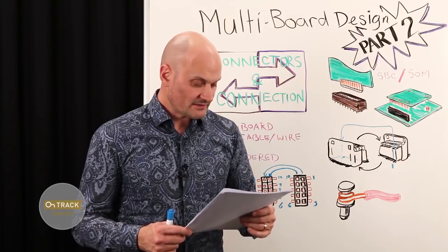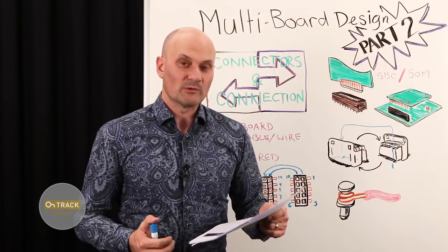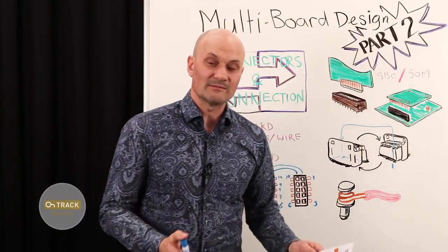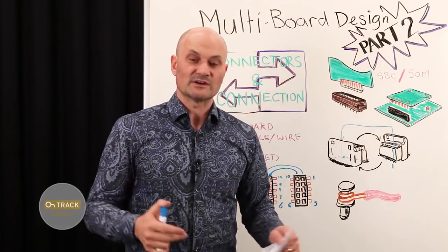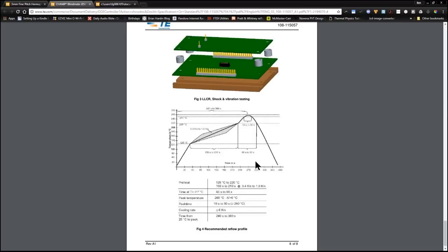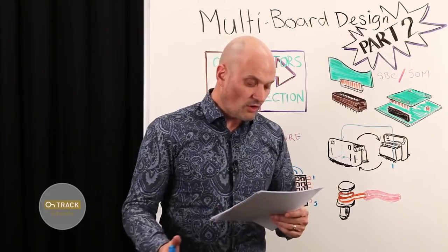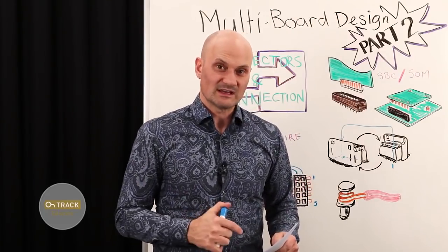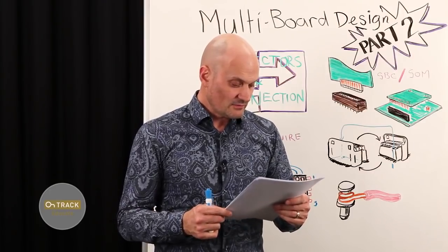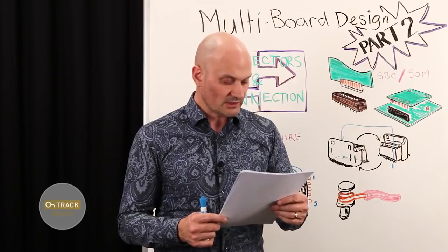And in addition to that, good manufacturers will either give you a soldering reflow profile for your assembly for the soldering oven, so you know what's the maximum temperature this connector can be subjected to during assembly for soldering purposes, or they'll tell you what the material is in the insulator. In the case of this Samtec header, it's the TSW I was looking at, it's black glass filled polyester.